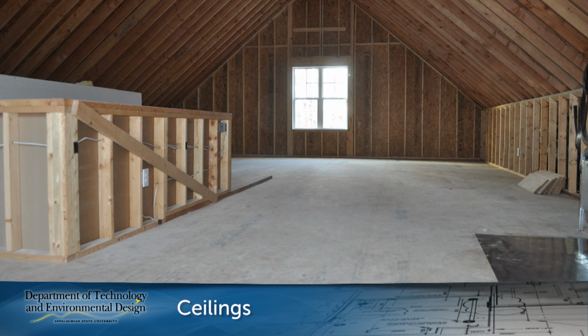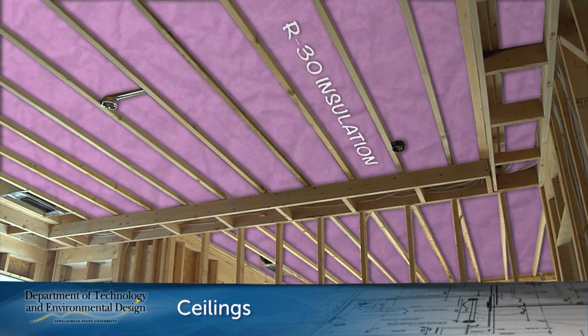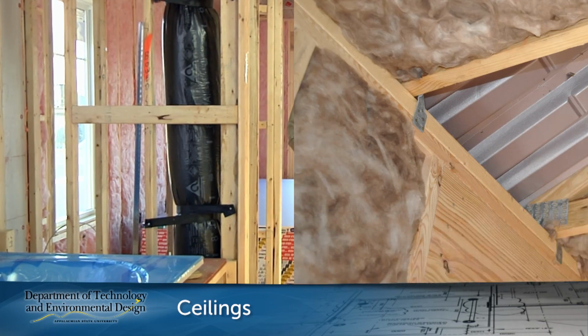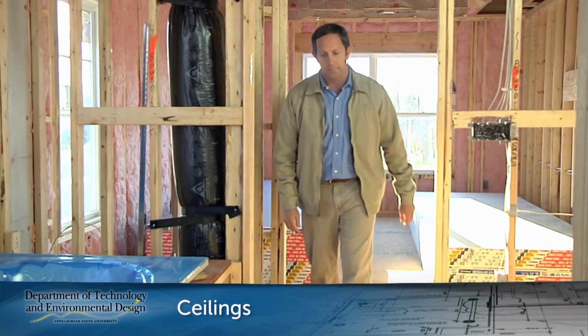In ceilings with attic spaces, when the enclosed attic space is fully enclosed, the insulation can be R30. Also, where space is limited, for instance where the roof, ceiling, and wall assemblies adjoin, insulation need only fill the space up to the air baffles. Let's go to the basement.